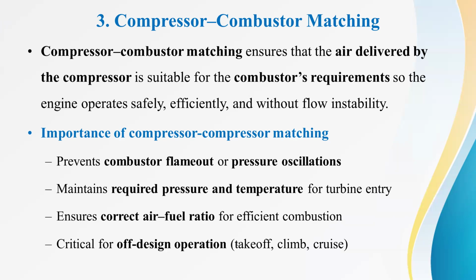So what is the importance of compressor combustor matching? One is to prevent compressor flame out or pressure oscillations. That means instability of the pressure. Again, to maintain the required pressure and temperature for turbine entry, and to ensure the correct air-fuel ratio, that stoichiometric ratio F, for efficient combustion. And finally, it is important because it is critical for off-design operations like takeoff, climb, cruise, and other conditions.